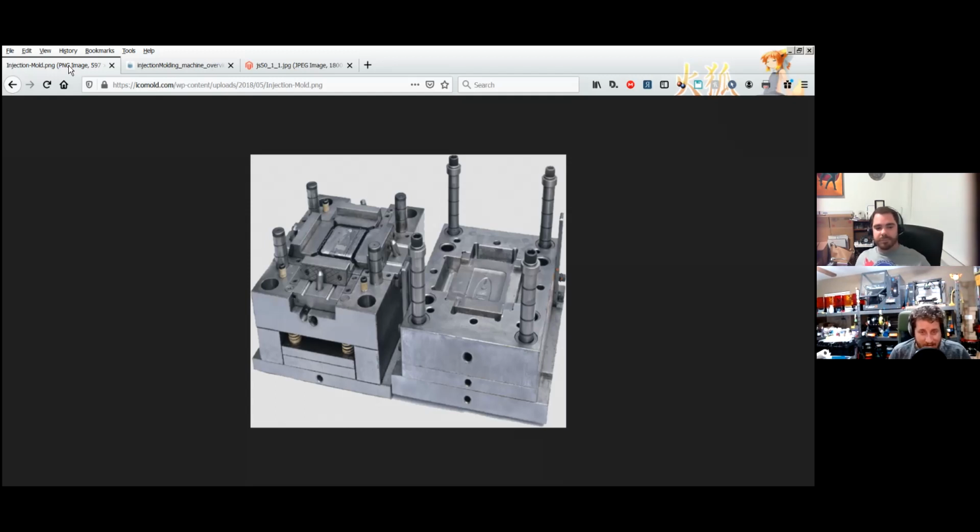The nozzle is the business end of the 3D printer. They range in sizes all the way down to like 0.2 millimeter. The largest one that we have that we use is 1.2 millimeter, which is capable of doing a 1 millimeter thick layer. Normally, 3D printers are doing 0.2 millimeter thick layers. It's 200 microns. For a size reference, the average human hair is 100 microns thick. A piece of paper is 100 microns thick. So put that into your head, right? So 10 sheets of paper stacked together is roughly a millimeter. That's how big of a layer this printer can do.